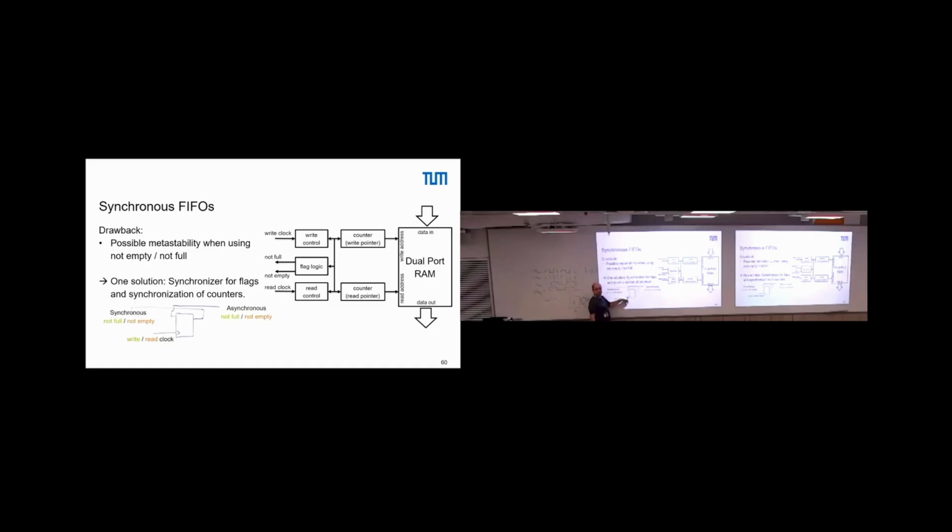So to update this full empty signal at the outside world all the time it changes, we need the clock from the respective domain. What did we say? The full signal is evaluated in the write domain. So we need to synchronize the full signal with the write domain.